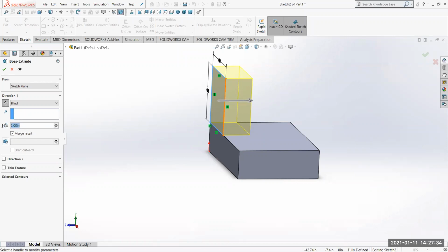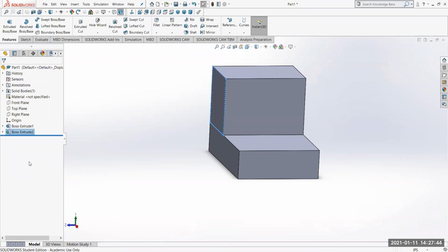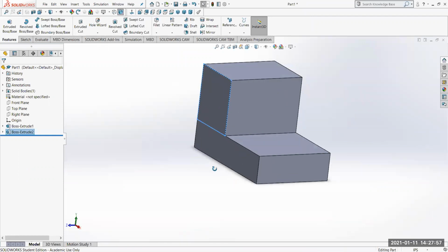So I'm going to say that the width of this extrusion is going to be 6 inches. I'll put that in at 6 inches. Check mark. Okay. And I'm going to cut this middle piece out right here. I can either do that before or after I make the roundovers. In fact, I might as well make the roundovers first. That way I only have to do it once.